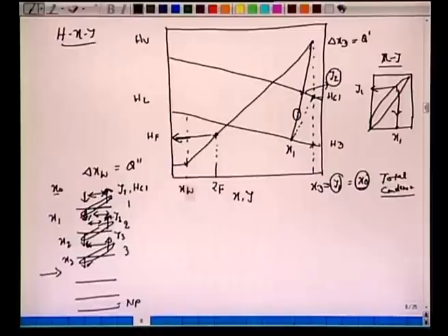Now this Y2, stage 2, is in equilibrium with the liquid which leaves this stage 2. So again we have to come to this XY diagram, obtain this Y2 wherever it is, get another X2 here, and we mark this point. So we have to make use of both the HXY diagram as well as this XY diagram. Both are in mole fractions. So knowing this, now we have Y2. Now we obtain this point which is X2. So we are here. Again X2 and the difference point we connect